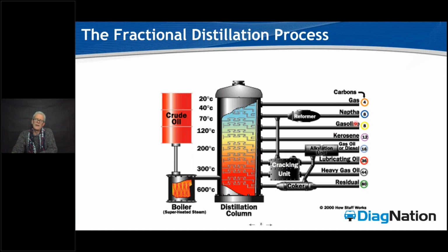Well, because of the shortage and the inability to use this gasoline that's naturally distilled at 8 carbon chains, what RFG rules have us doing is cracking fuel down further in the barrel into the thicker base to get the base for the fuels. Now, let me just explain really quickly how that works. This cracking unit's actually called a hydrocracker, and it's cracking with hydrogen. So one of the first problems with this process is we're having a precursor to a water molecule distilled into the fuel base by virtue of how it's being made by the cracking.